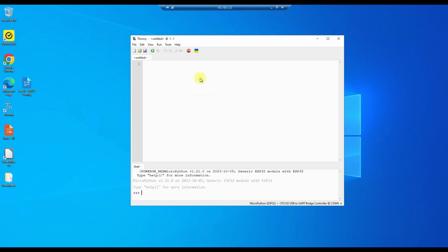That allows other devices to connect into this microcontroller, which is not something we want for this exercise. And then the second mode is station mode. That isolates the microcontroller. It allows it to connect out, but doesn't allow connections to it. So we're going to use station mode for this exercise.